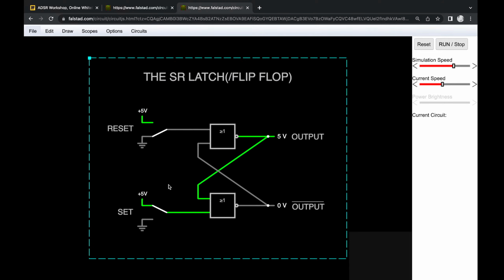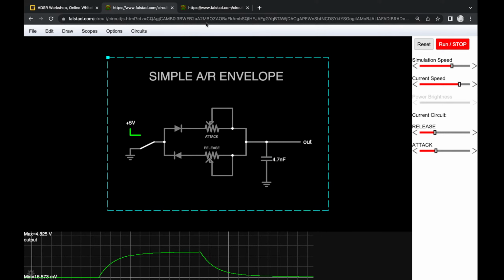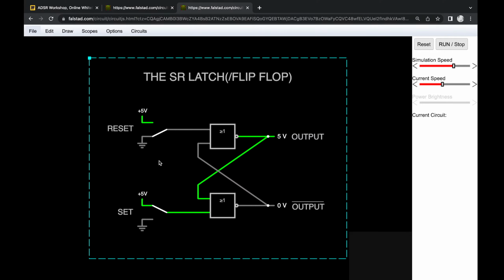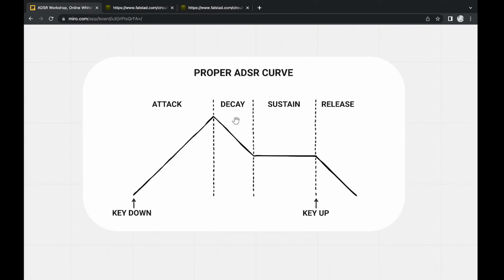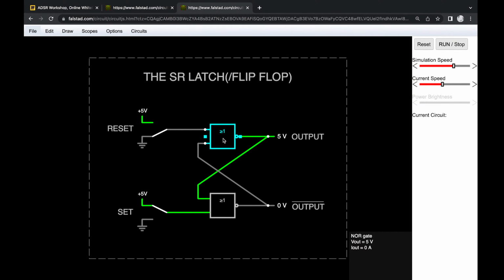And by the way, this works because a flip-flop has a threshold at both of its inputs that determines when it considers a signal as a logic 1 or a 0. So if we wired the output of the envelope back to the reset pin, then this reset would only get triggered after the output has passed a certain threshold. And that is the way that we know when we've reached the peak, and then we can start doing something else. And if that was confusing, I completely understand.